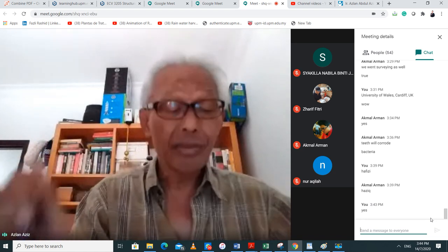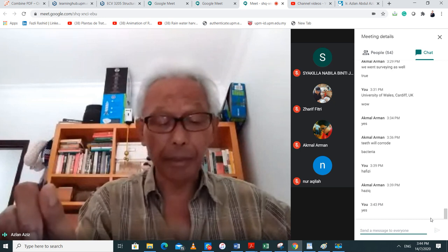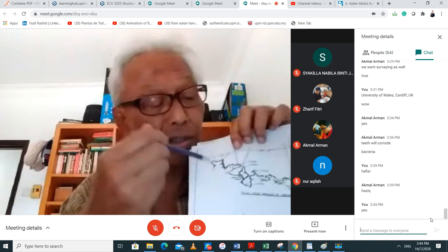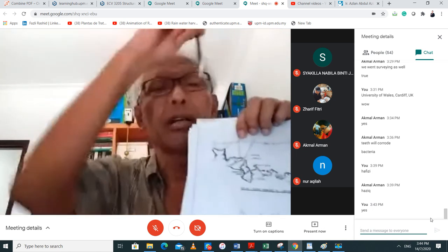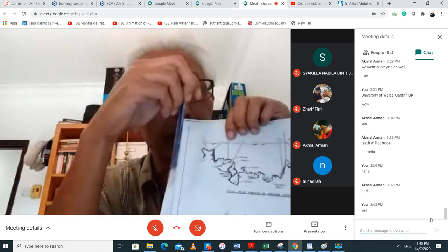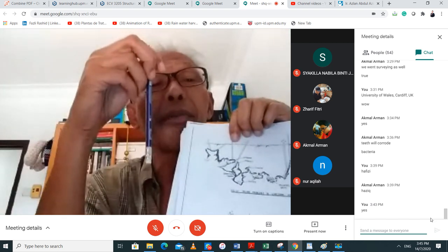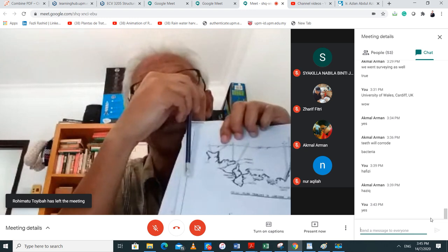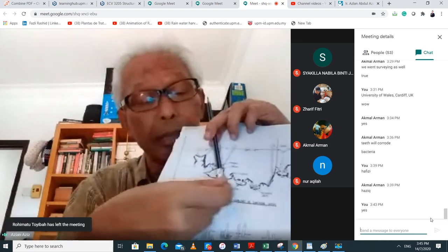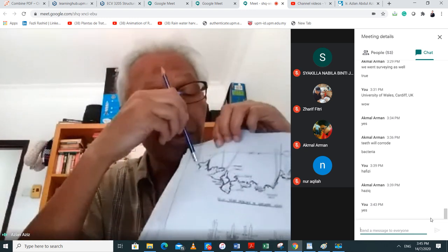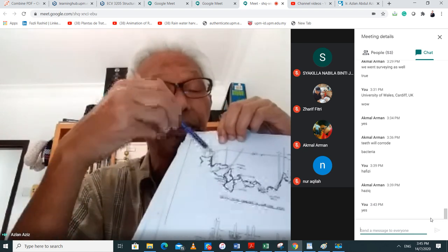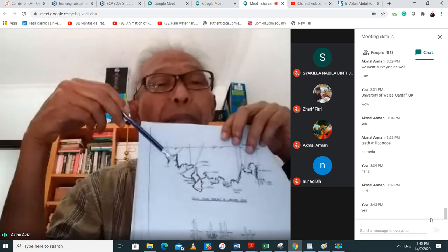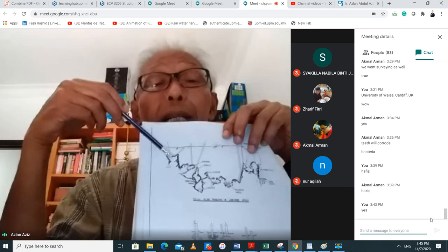Okay, guys? So anyway, you look at piling problems in limestone areas. Now, in the one here, the cliff is shaped like that. You're thinking of putting your pile straight down, right? Because you're thinking of having a bearing capacity type of pile, the one that obtains the ultimate bearing capacity from the tip. All right. And what instead happens is that it goes through this cliff and comes out here. That's not what you want, right? Is that what you want from your pile? Definitely no, right?